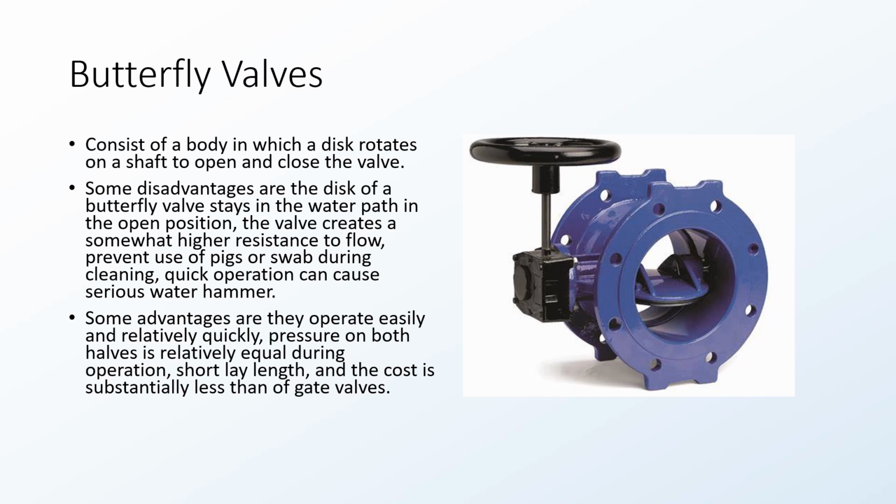But the advantages to them is that they're relatively cheap when compared to a gate valve. When you operate them, you have pressure on both sides of the valve, so you don't have a lot of resistance as you're operating this type of valve. So that's a couple of advantages to them.